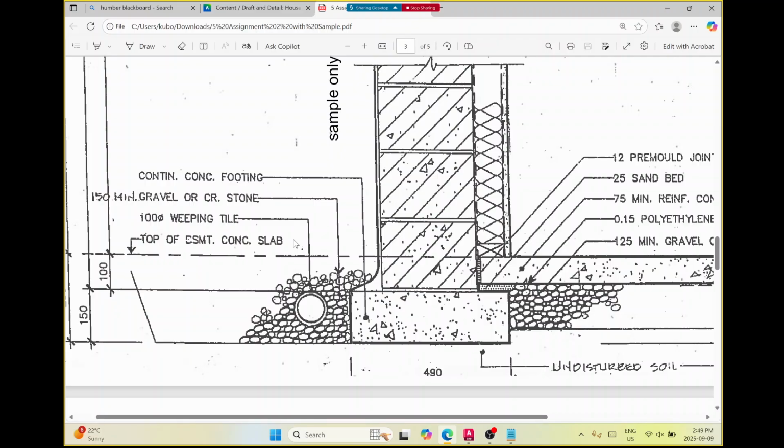When you see this pattern with the dots and the triangles, that typically indicates something's made of concrete. Diagonal lines mean it's a brick or a block. If they're closer together, it's a brick. If it's further apart, like this one, it's a block. So this one has concrete hatch and diagonal lines, so it's a concrete block.